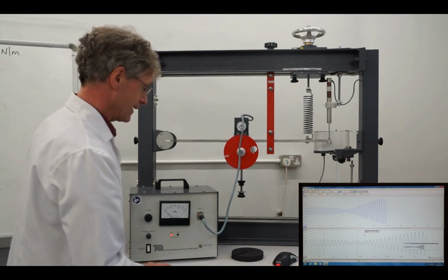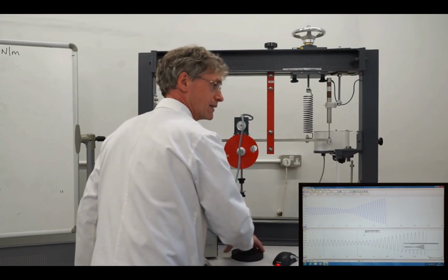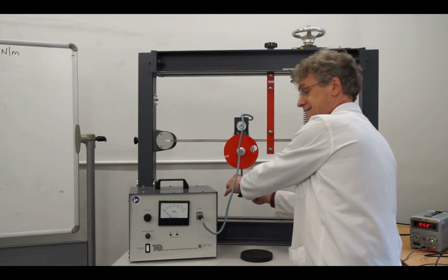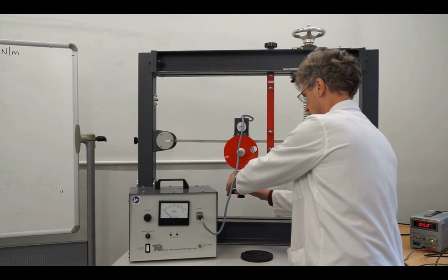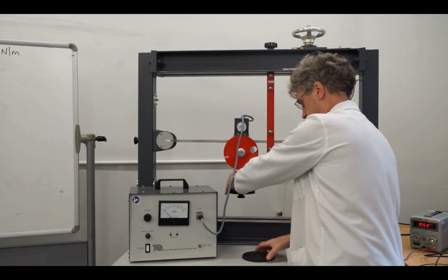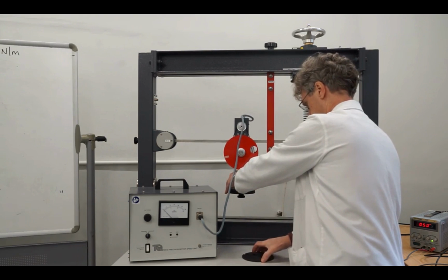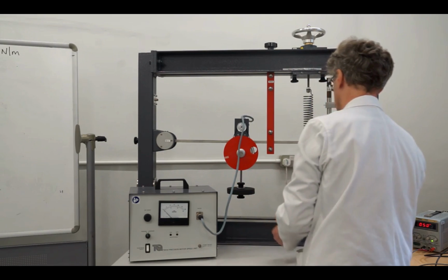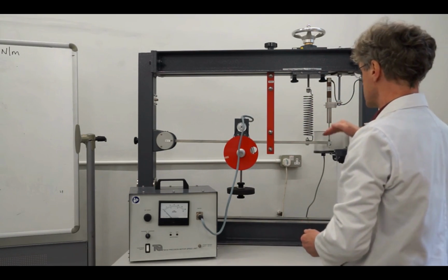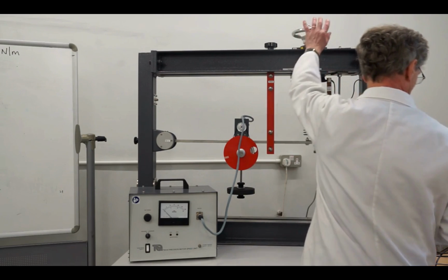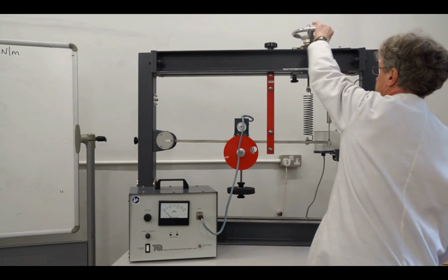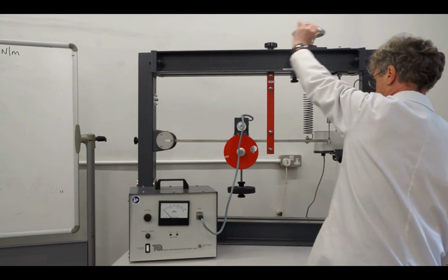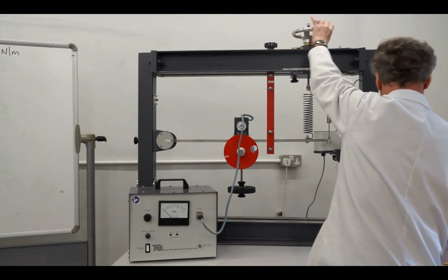So now we're going to increase the mass on the motor. We're going to increase it by 2 kilograms. So we're placing these individual weights on, and then we're going to lock to secure the weights in position. The beam is dropped, so we now need to bring the beam up into somewhere in the midpoint. We do that by bringing this handle, which then raises the beam to approximately the mid position.